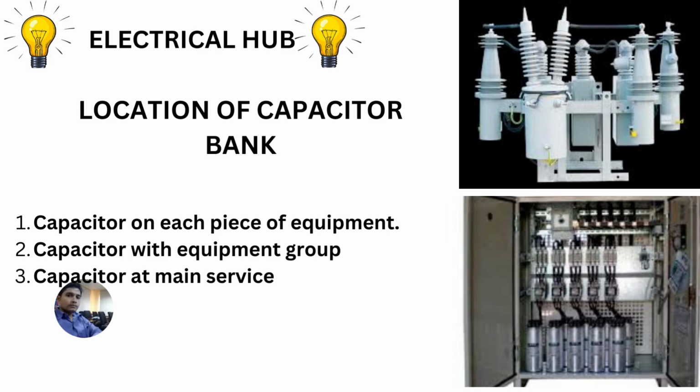First, going with the advantages, it increases the load capabilities of the distribution system. It can be switched on with the equipment and switched off with the equipment. Better voltage regulation, capacitor sizing is simplified, and capacitors are coupled with the equipment and move with the equipment if rearrangement is done.